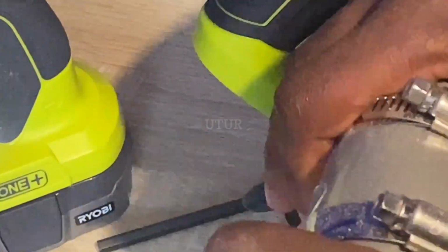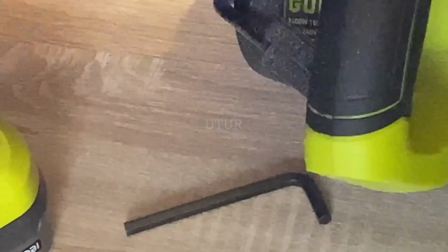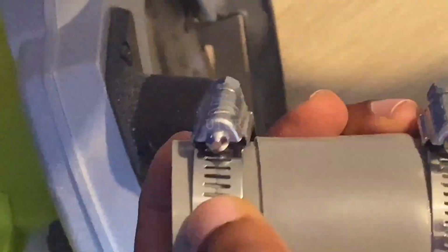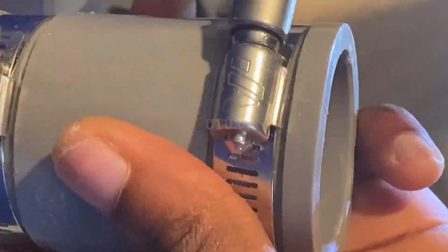Okay, you can store the coupling away or leave it installed on the vacuum adapter, provided you haven't got the hose on it. That's fine if you regularly use your circular saw. But if you don't, just store the coupling away on its own or as a standalone from the circular saw. Then subsequently disassemble the coupling from the vacuum adapter by undoing the knots. And whilst undoing the knots, if the clips on the coupling disengage fully, bring them quite close to each other and tighten the screw, and the clip should get back into position.